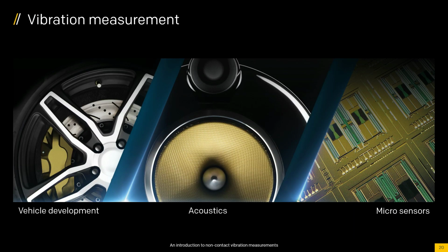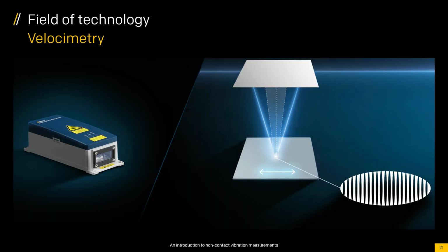And there are a couple of ways to look at this. Number one, if you go back to the schematic of an interferometer, the vibrometer doesn't know the difference whether the structure under interest is moving or the vibrometer is moving. It's going to consider both as the same. So what do we do?